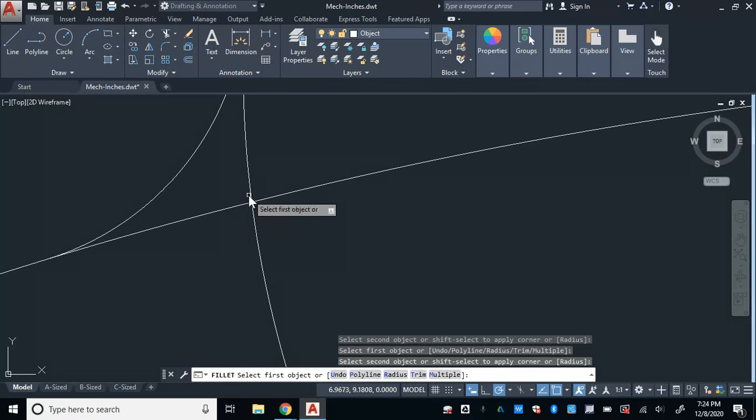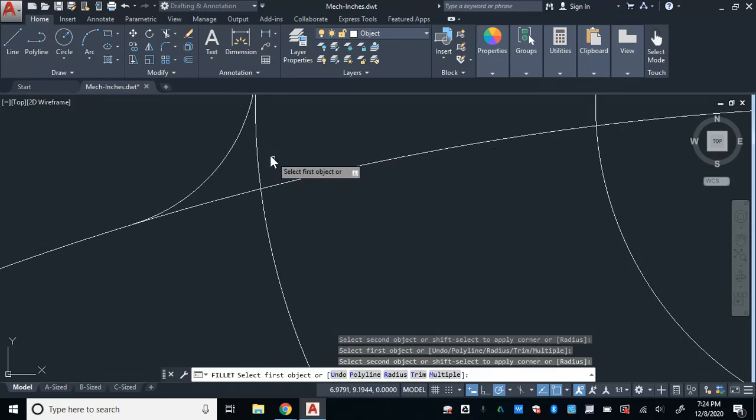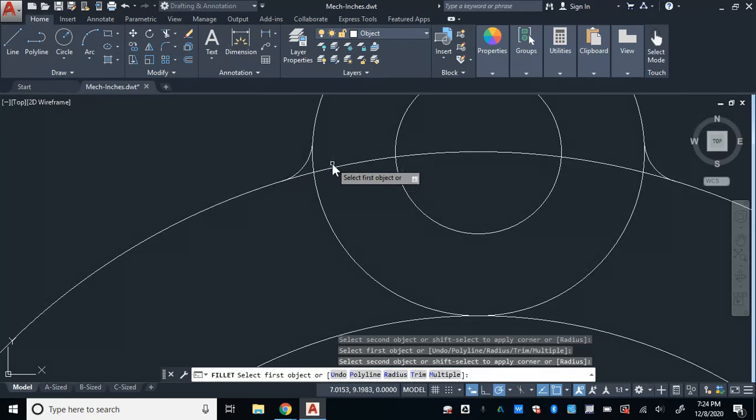The sharper the angle, the more prone it is to tearing and ripping. So if you didn't put the fillets in, why would it rip? It would rip right here at this corner and cause the gasket to fail prematurely. By putting a fillet in and giving it a nice smooth curve, you're actually making it stronger and keeping it from failure in the future.